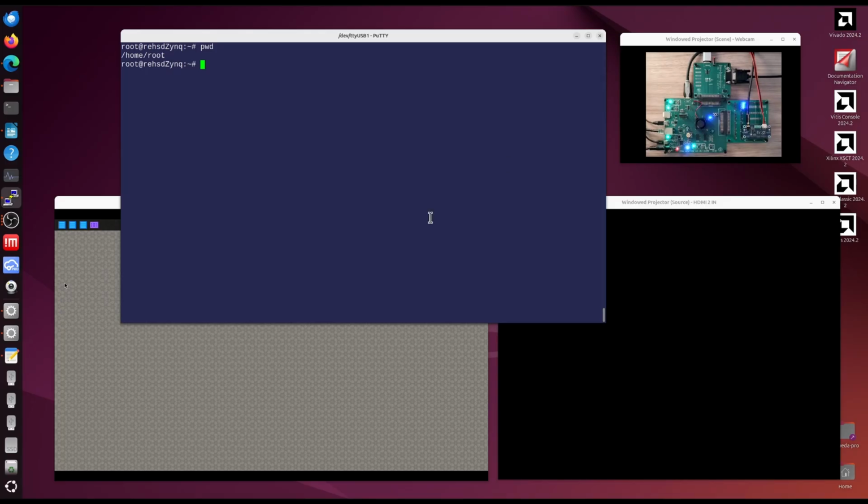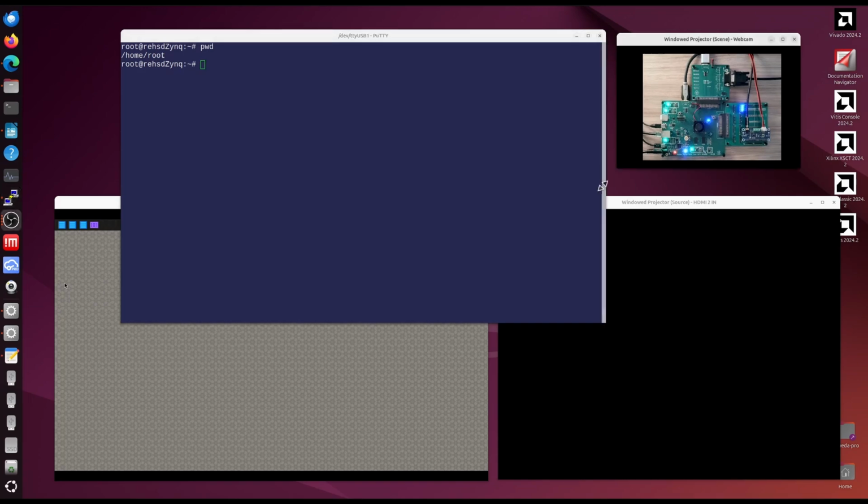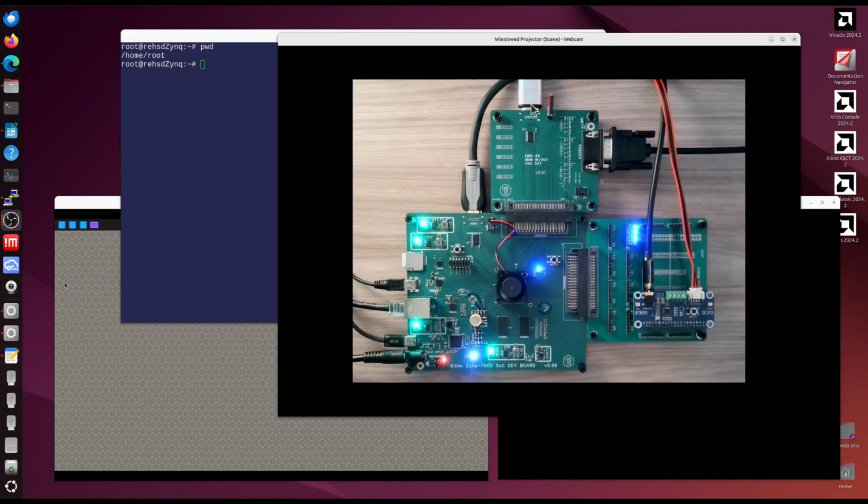So this is my first, this is my second, and that's my console output. I also configured the system through Weston to say that this is the output I want to display the user interface on. So the intention is that when I boot up the system, I'll see it boot to this output, and then it'll flip over to the graphical user interface, and that'll come out of this output.